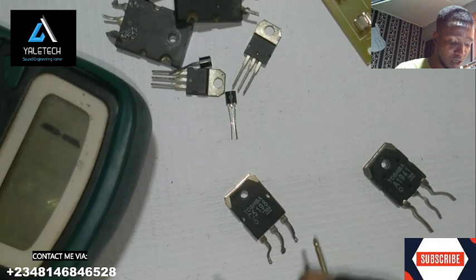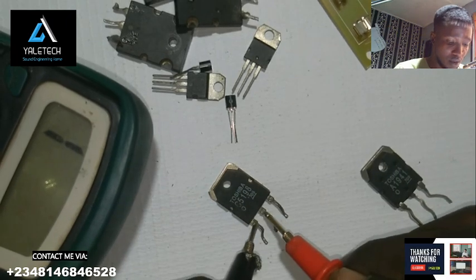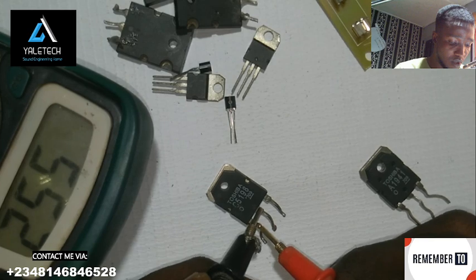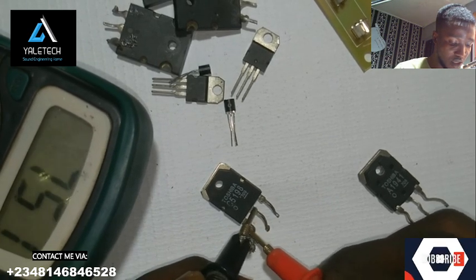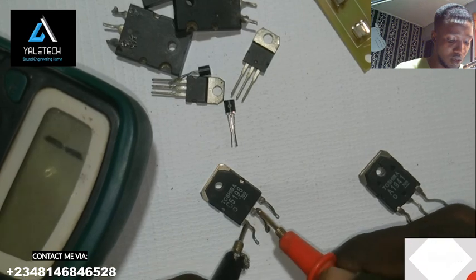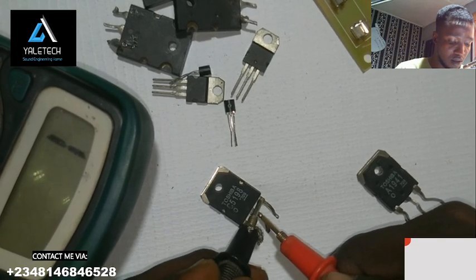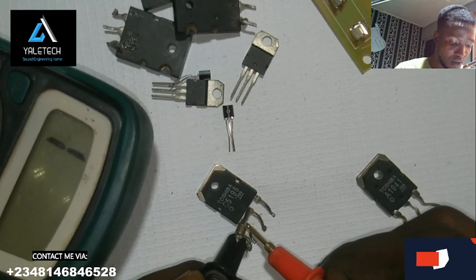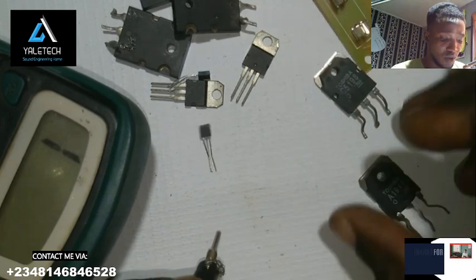Now let's change our probe to the other way around. Look at it now. You know, at first it was reading this way, but this way it must not read. If it is reading in both directions, that is to tell you there is a problem somewhere. You understand? See? So it's reading in just this direction of the emitter location. You understand now? So this transistor is still a very good one.